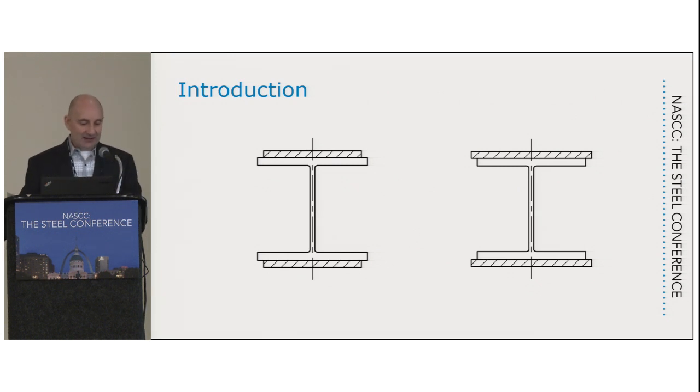Now, this is my favorite reinforcement type, the one on the left-hand side there. The reason is because it's easy for me to design, and it's pretty easy to install. You only have 2 plates, and typically that edge between the flange tip and the plate, you can make big enough, maybe 1 inch or so. The AISC manual might say somewhere around a 1/2 inch for certain size welds, but you want to give them room to move that plate around a little bit in the field too. So that's my favorite type.